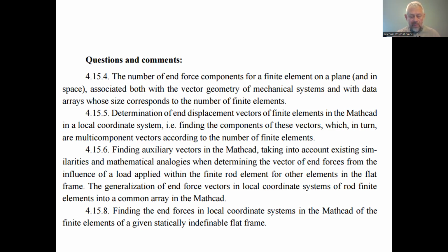The generalization of end force vectors in the local coordinate system of rod finite elements into the common array in Mathcad. To do that, usually we can use consequently 3 times the if operation, if we have 4 types of finite elements. The parameters of the if operation in the brackets: the first is the condition, whether it is true or false, and next after the comma we have the definition if the condition is true, and after the second comma we have the definition if it is not true.